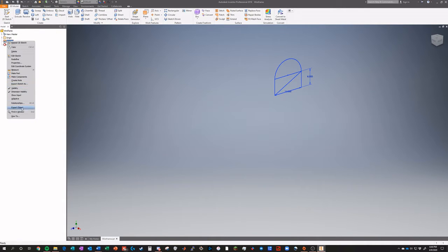Another thing that will save you a lot of time and stress later is naming all your sketches. So if you double click on it, there's probably another way to do it as well, but by double clicking I'm just going to rename it roll hoop plane. It also might be worth your time if you want to make the roll hoop its own thing and then add these others as separate deals and label them as such. That could save you a lot of time as well.